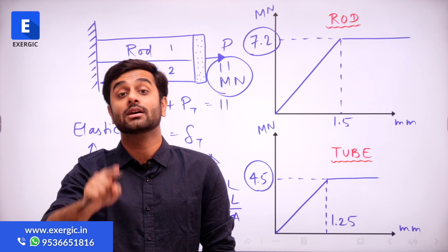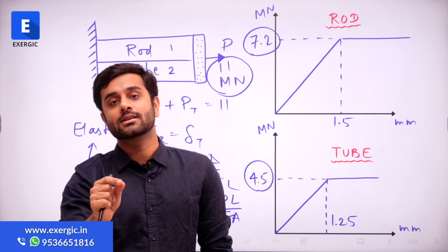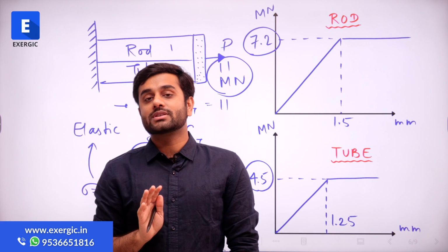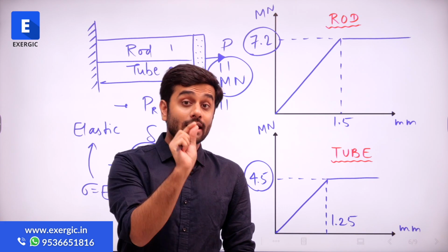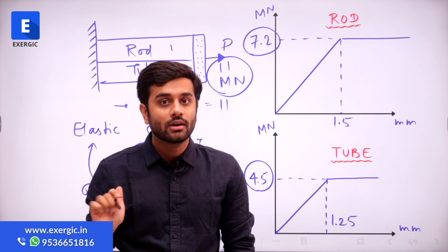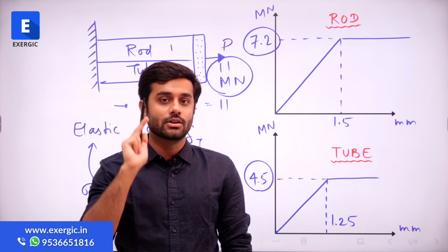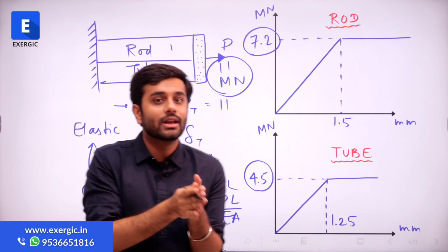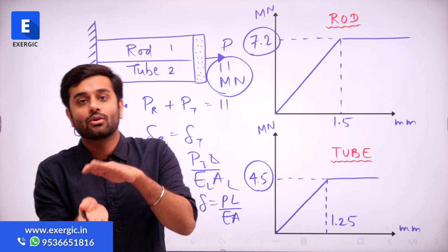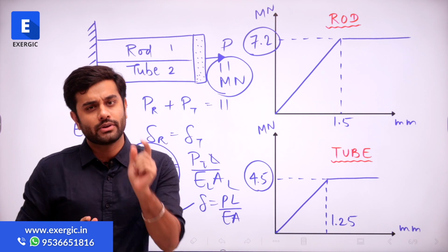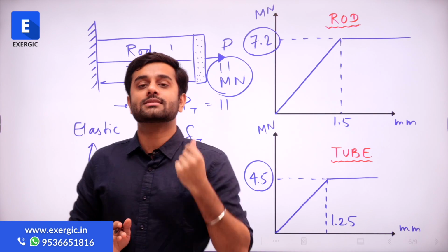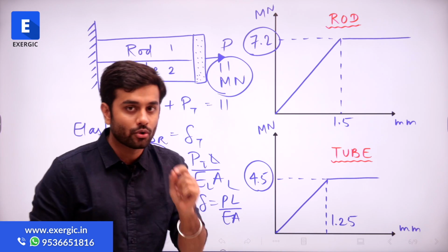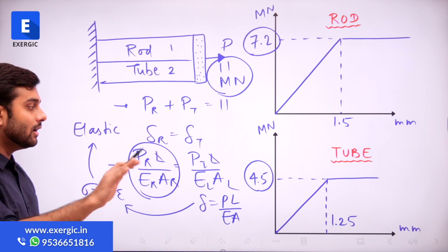Especially if you get a question where a load deformation curve or stress strain curve is given to you, and the plastic region has clearly been shown. In every such question, you have to pay attention and notice whether the loading is in the elastic region or it entered into the plastic region. A very small thing to notice, but it will change the answer totally. So it's an important learning for you. Make sure to write it down in your numerical learning notes.